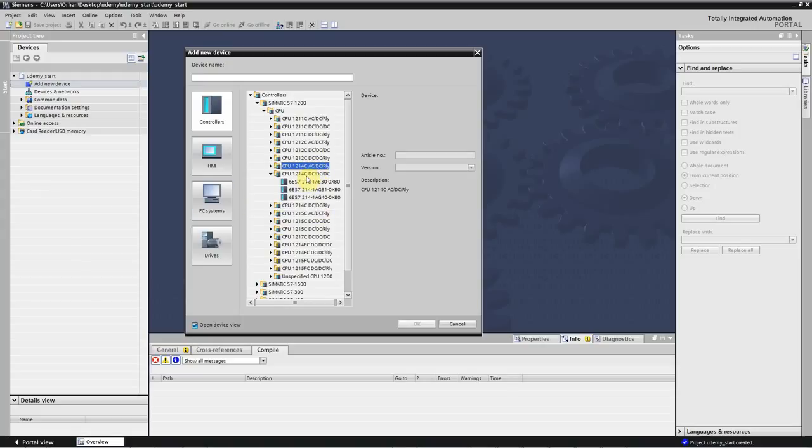After that we will learn other different systems, and you will see what we can make with them. And the second DC means inputs. Our digital input is DC, so we will use 24 volt inputs. And the last DC means output: this PLC CPU has transistor outputs. Because of this, we see this last DC.